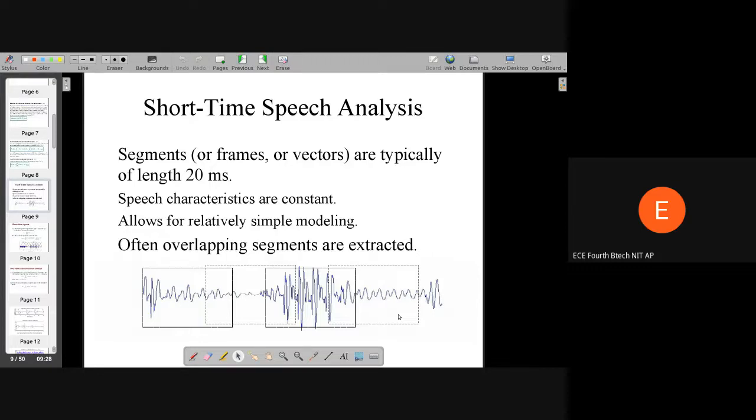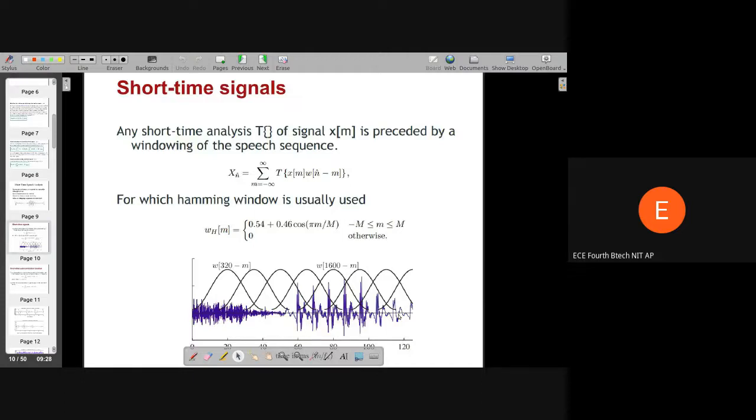The first thing is you take a frame of a speech signal. Now you could put a rectangular window, which means it does nothing. Putting a rectangular window and doing framing is exactly the same thing. There's no extra thing to be done. But if you put a dome-shaped window, like the Hamming and Hanning we talked about, the signal in the center of the frame is emphasized.